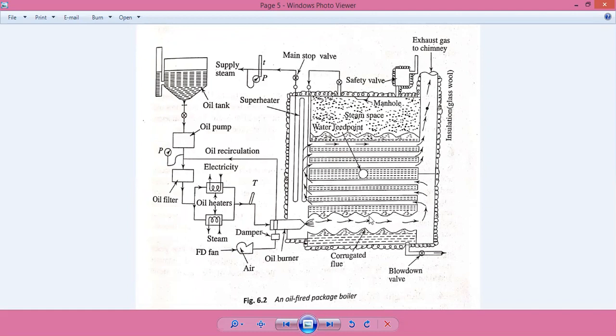It goes to the furnace itself. Then from the furnace it goes through the passage. It goes inside these particular tubes from here, here, and here, and is then recirculated again through this tube, coming out and exhausted through the chimney. These tubes are in direct contact with the water for boiling, and the heat from the tubes is transferred to the boiler water, which gets heated and is converted into steam.